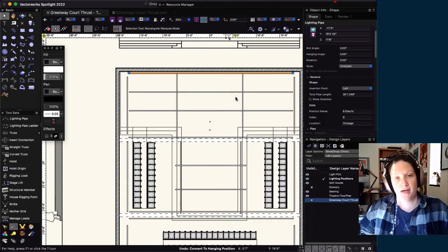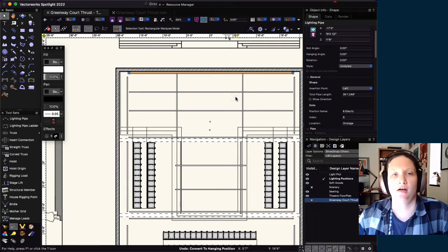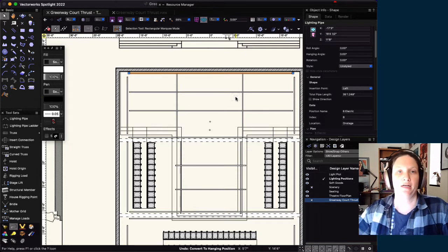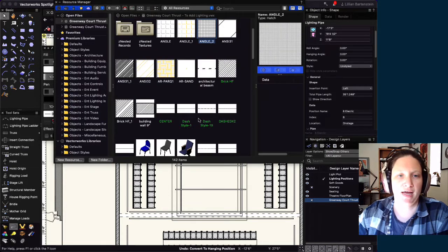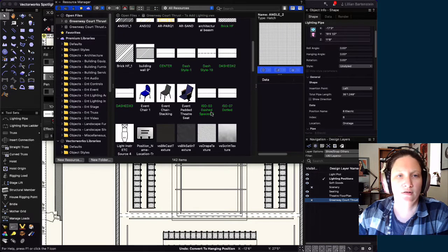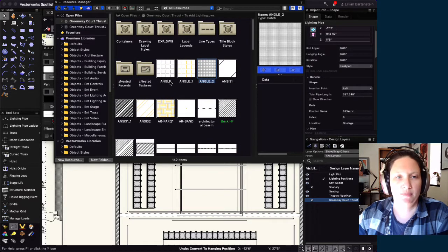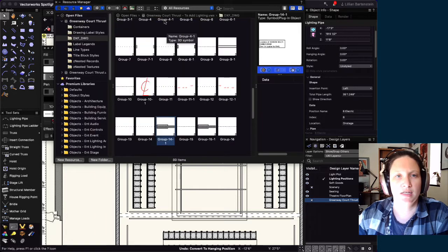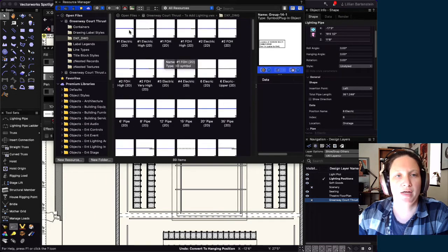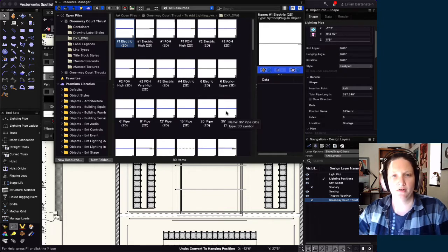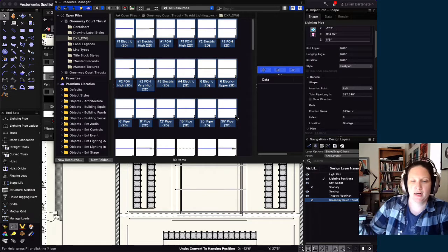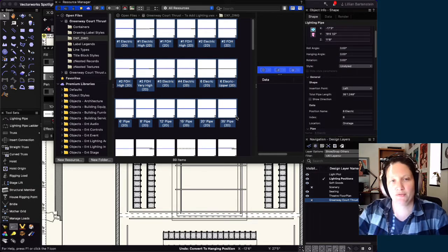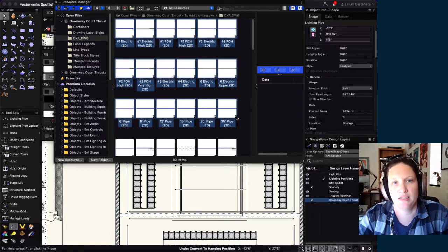So now that you've added all of these lighting pipes, our next step is going to be to convert them into hanging positions. And you'll notice actually in your resource manager, there's a little bit of mess already happening, right? If you scroll down through this file, it may be hidden in this DXF DWG section. We already have a whole bunch of random pipes and lighting positions and 2D, 3D symbols. These were all imported as part of the project when we imported the DWG file.